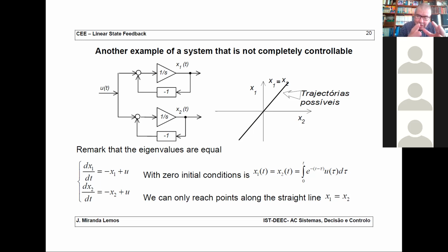Instead of making the system very well insulated, which he was never able to do, you should remove the insulation so that the actuator, that is to say the heater, is in contact with the reactor. So if your system is not controllable, you should be careful. First, check whether the actuators are where they should be. And second,